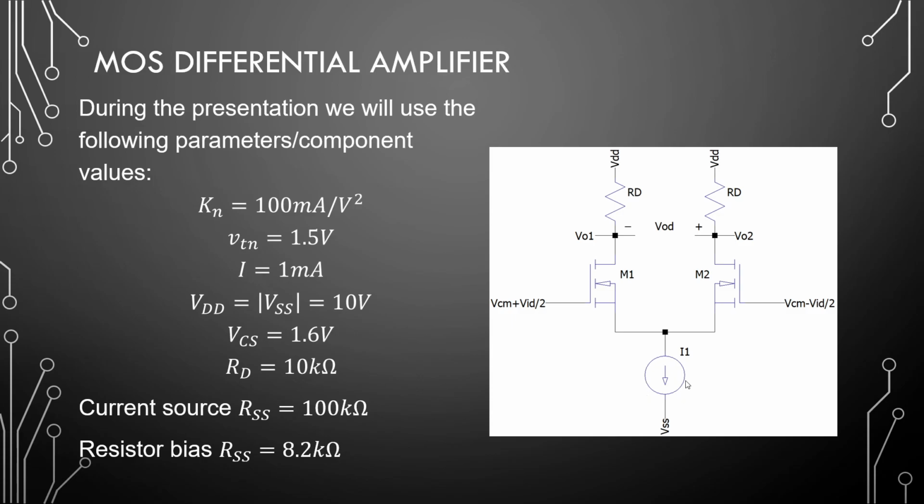But typically some form of current source which will sink current from both sides of a circuit and provide the bias. The differential amplifiers do not need external bias resistors like we had. They are self-biasing. That's one of the advantages of using differential amplifiers like this.